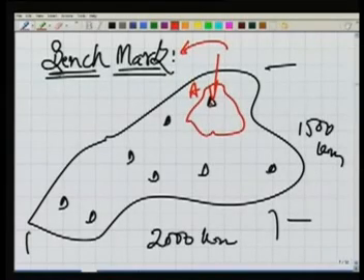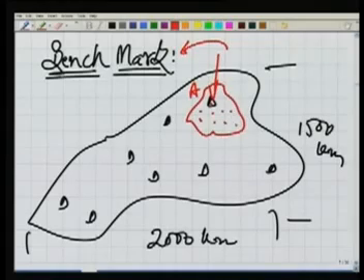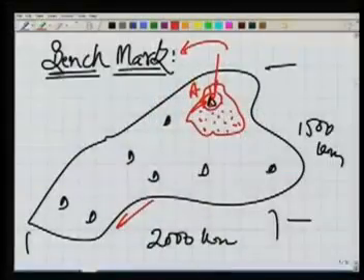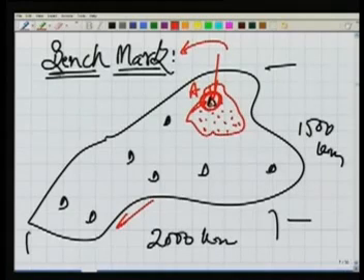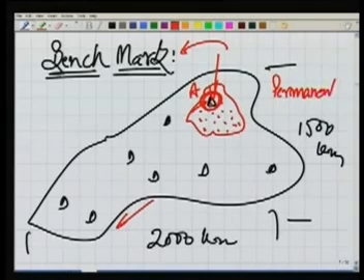Now these benchmarks serve a purpose: we can use them and refer other points to them. I can now find the elevations of all these points in relation to this. I need not go all the way to the main benchmark there. Rather, I can do my survey with the benchmark here. This kind of benchmark is generally called a permanent benchmark, which is established permanently.